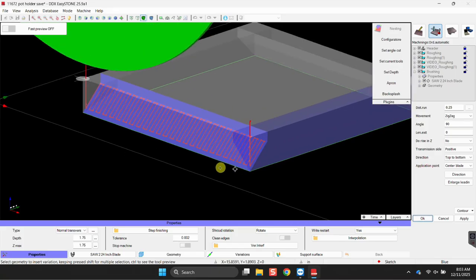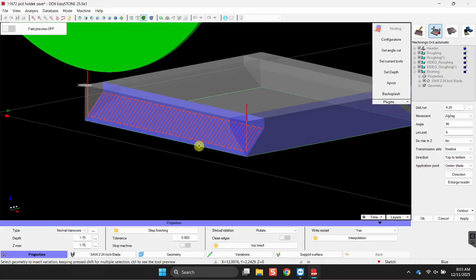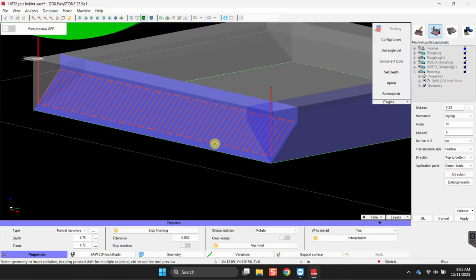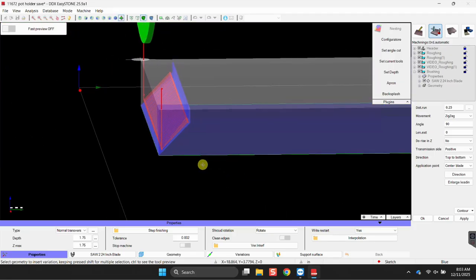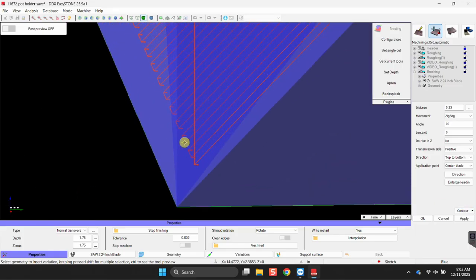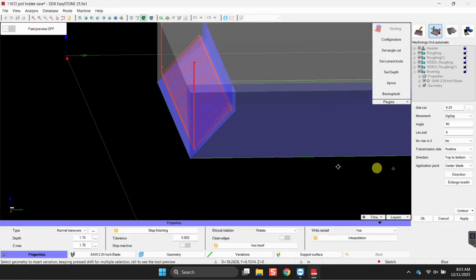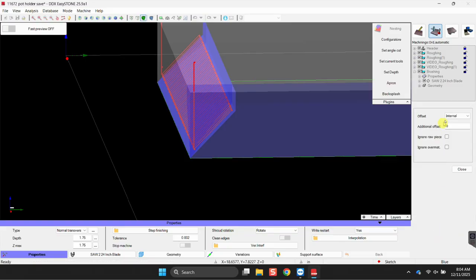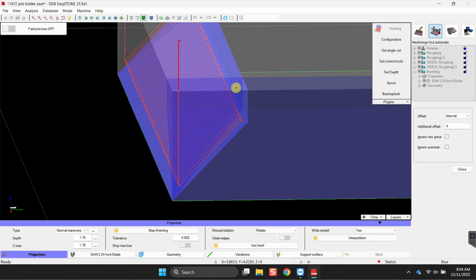So right off the rip, we can see this kind of happening where this might be a setting that we have going on, but it's going to be in our contour. What I'm seeing is that it's not coming all the way down to the edge. It's kind of stopping short here. So if we go into our contour settings, we see a surface's contour is being applied, and we're telling it basically stay inside of this edge.